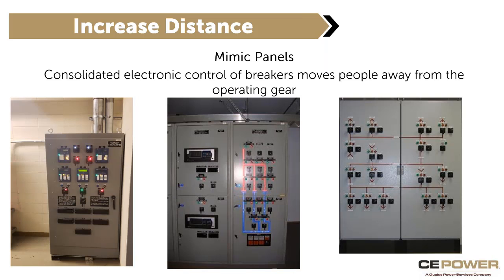Mimic panels, again, this is technology that's been around for years and years and years. Getting the relays and the breaker control switches, and even on the left there, you can see an installation we did for a pharmaceutical company. You're getting the test switches away from the switchgear, so we can actually test the relays, test the circuit, open and close the circuit breaker, adjust settings, with control wiring going into the switchgear or the breaker cell, and then away from the switchgear, so that when you're doing that activity, you're away from the circuit breaker and the bus.